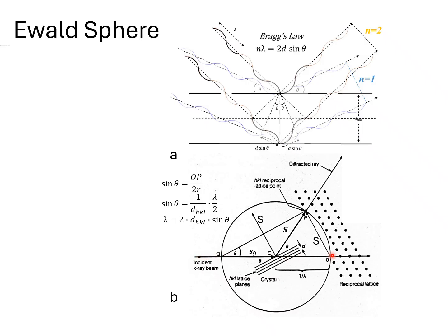So we start here, and it turns out that if we take a vector from the origin to some reciprocal lattice point corresponding with diffraction of a particular angle, a particular Bragg angle, we excite that reciprocal lattice point for a particular geometric configuration of the crystal, given the wavelength coming in and sampling the wave going out.